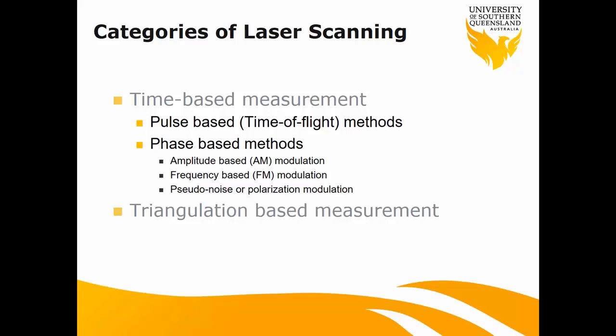We measure this frequency shift and indirectly measure the travel time. In this way we can increase the time measurement accuracy up to 100 times. For laser scanners currently, you will see some examples shortly in the following slides. The pulse-based or time of flight technology is used by some laser scanners.